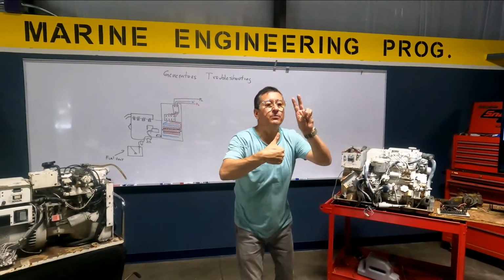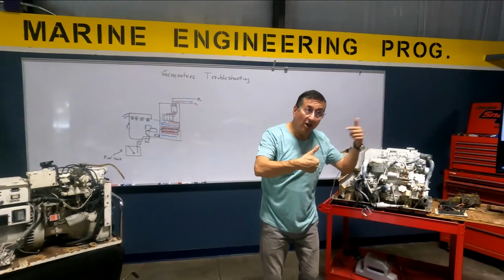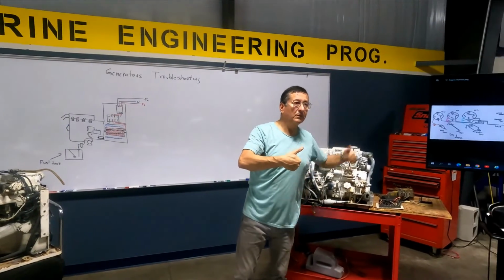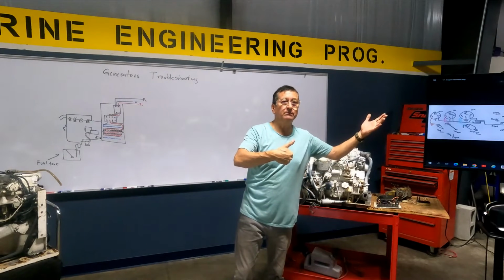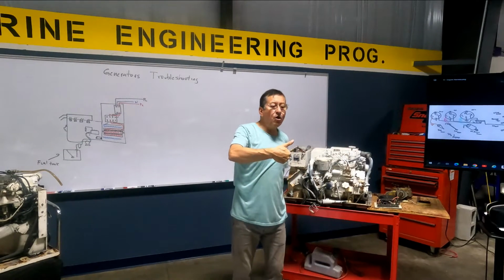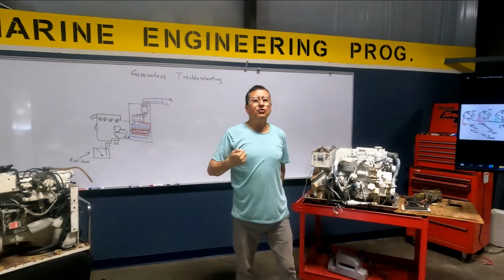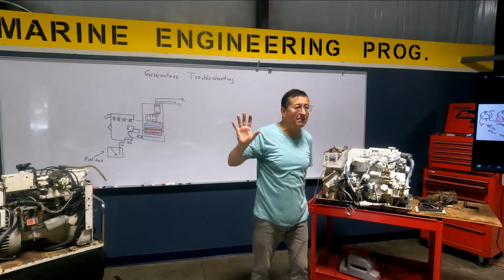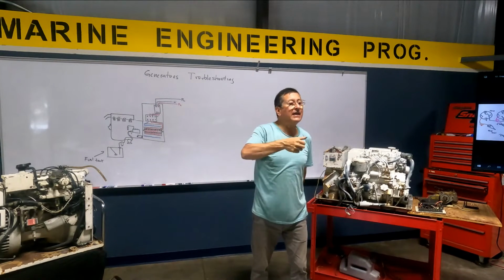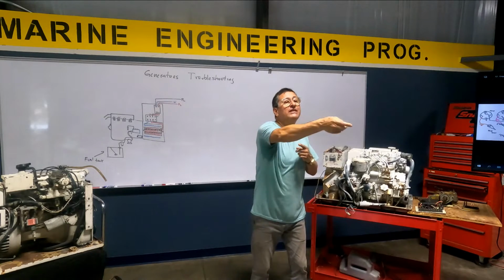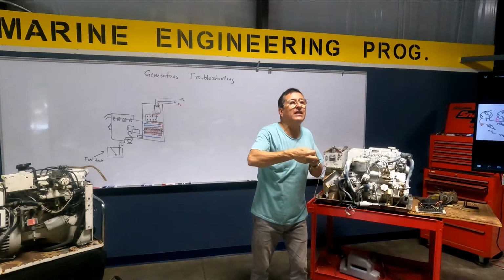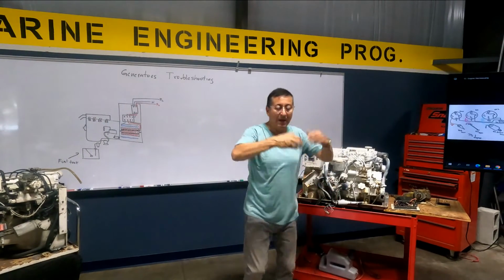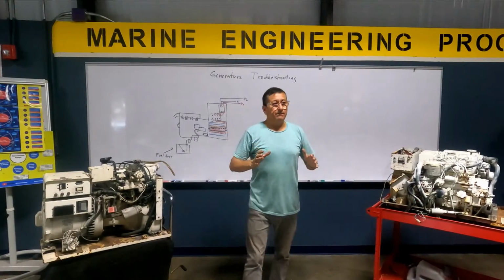You use that preheat button for two purposes. One purpose is to preheat the glow plugs, because it is diesel, and the other purpose is to bring fuel to the fuel injection pump and solenoid. That's okay? Okay. For two purposes. When you remove your finger, Mr. Garfield, you don't have glow plugs because you don't need them. You produce the first explosion and you don't need more glow plugs. And right now, you can remove your fingers because the alternator is sending power to the relay, and the current continues into the solenoid and into the transfer pump. Bingo! That's the function.